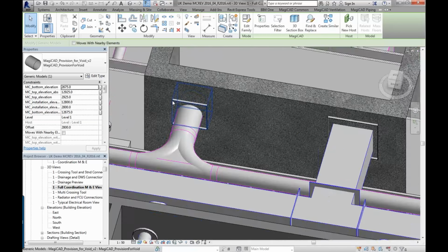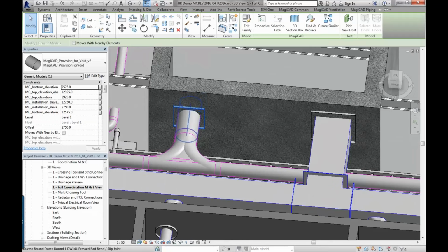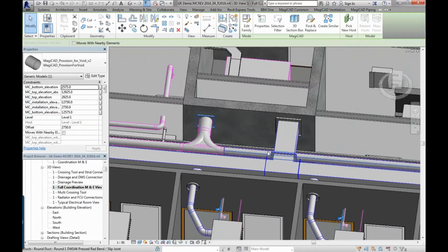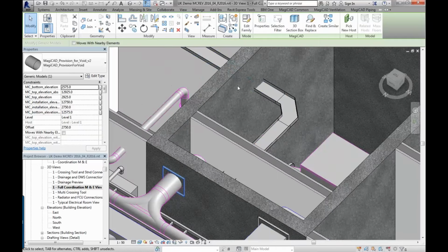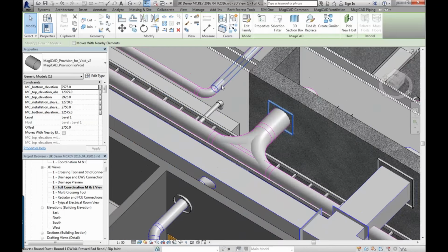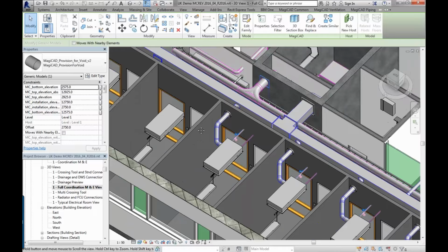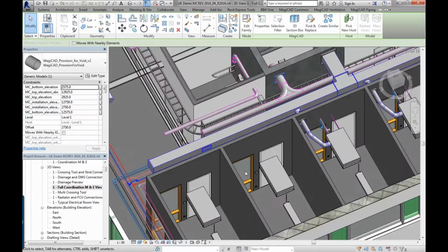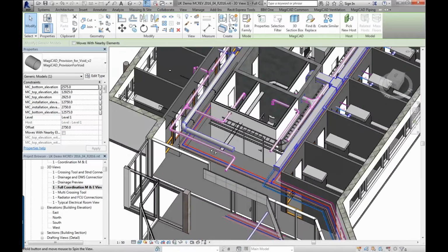You can see here you've got a square or rectangular hole request, even though it's a circular object, because clearly that exceeds the limit of 250 we put into the settings previously. There's a square one there anyway. You can see it's missed a cable tray out because that wasn't visible in this view, etc. It hasn't put the void in there because the size of the void would be below the required minimum size for the void that we put into the data set. So you can see how all that goes together in that manner.